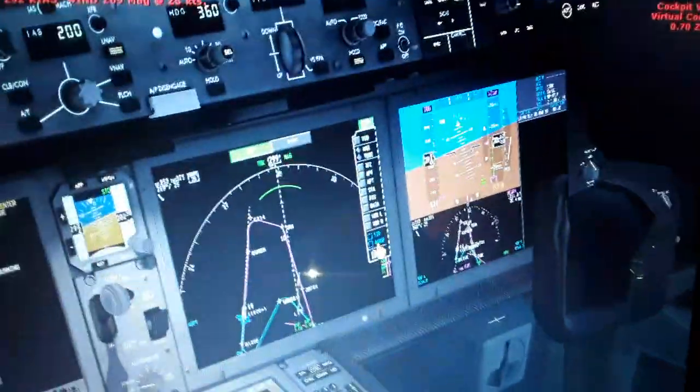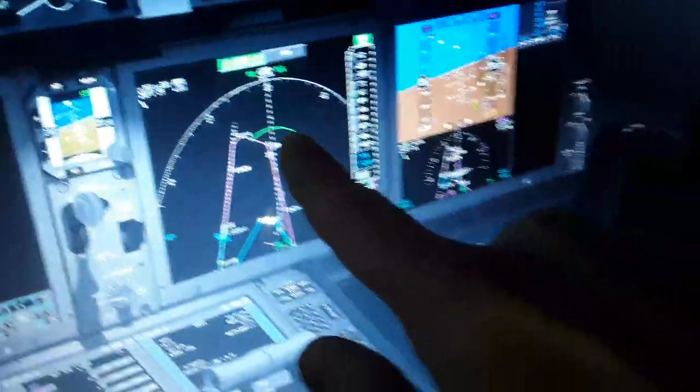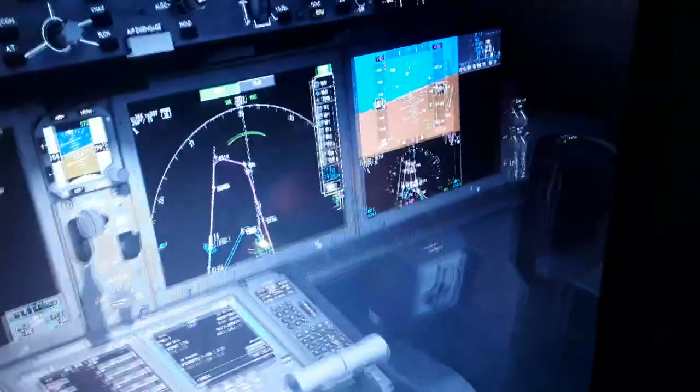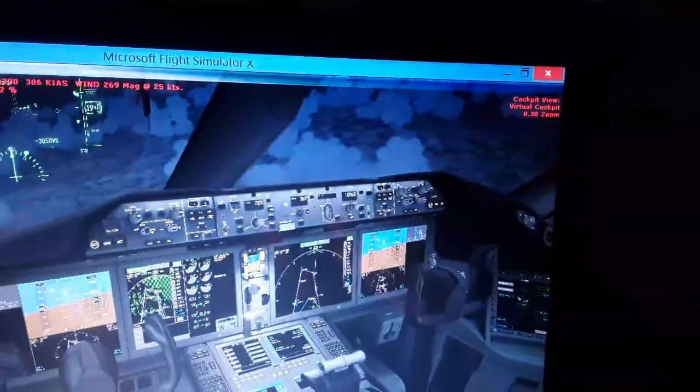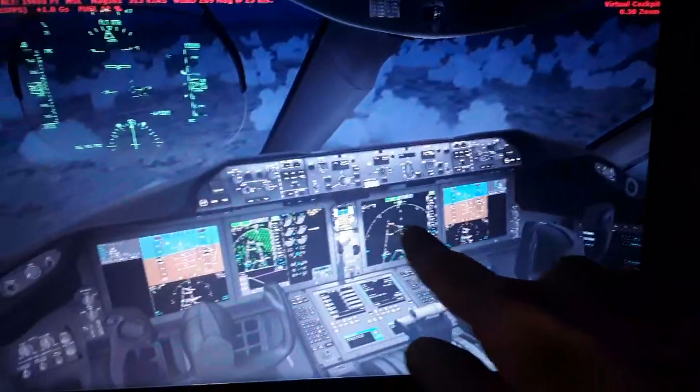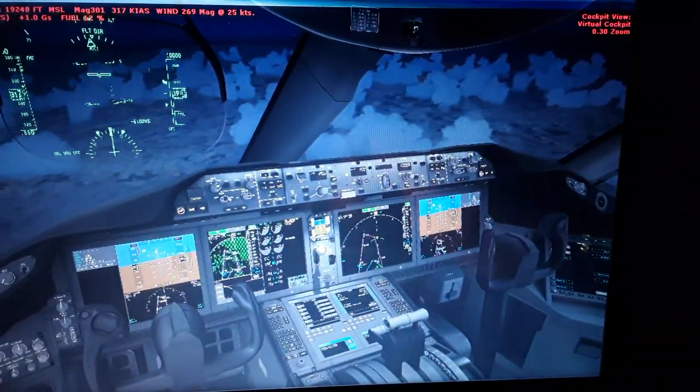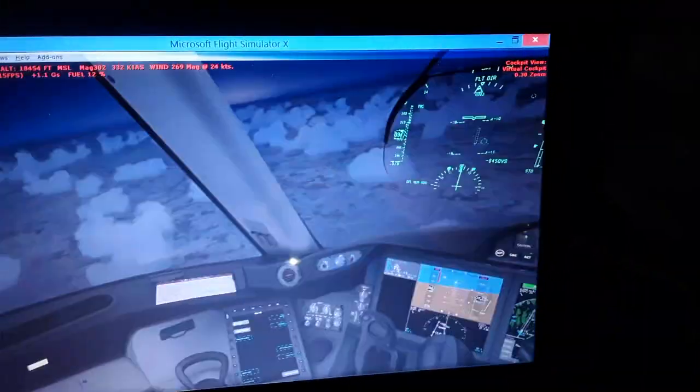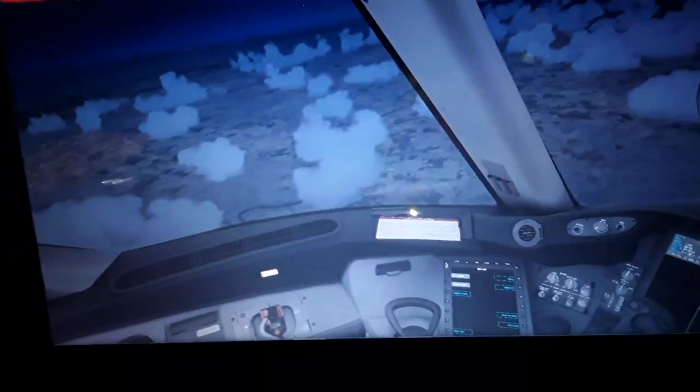You can see this shows where we're going to be descending using the current altitude and descent rate right now. So we need 10,000 feet. We need to be right here. I'm going to have this airspeed. We're going to increase the rate of descent. I'm going to be going faster, higher airspeed also.